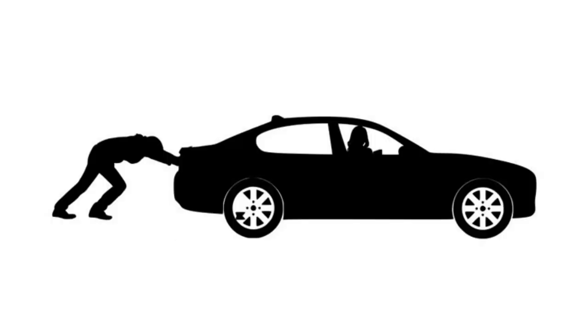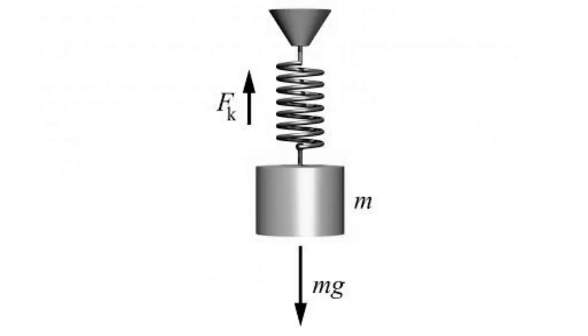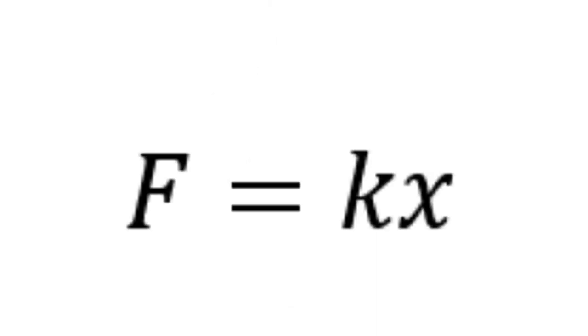In many practical situations, mechanical work is done by a force whose magnitude does not remain constant over the entire period during which work is being done. In these cases, it is possible to consider the relatively simple but useful case of work done in deforming a coil spring. In this case, it is found that within the normal operating limits of the material, the force required to produce axial compression or elongation of the spring is directly proportional to the amount of deformation, which can be expressed as a formula, F = Kx, where x is the amount of elongation or compression, F is the force corresponding to the amount of deformation, and K is the constant of proportionality, or known simply as spring constant.